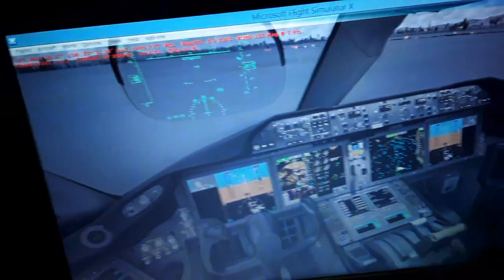We also have the ILS localizer crossbars for guidance, and the ILS localizer frequency and name displayed in the primary flight display. We have the flight director crossbars for manual guidance of the aircraft and the autopilot crossbars for automatic guidance of the aircraft. We have the flight mode annunciator with the autopilot, auto throttle, and lateral and vertical navigation modes, and also the integrated display that shows the magnetic compass and the flight plan we have created. So you can see all these things here in the primary flight display.